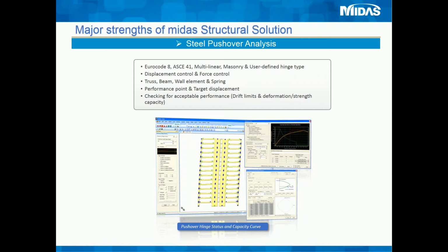Under advanced analysis, steel pushover analysis for performance-based design can be performed in MIDAS Gen. The good part is the hinge properties can be automatically calculated by the program, and as a result, the program provides the hinge status results and the performance point from demand and capacity curves.